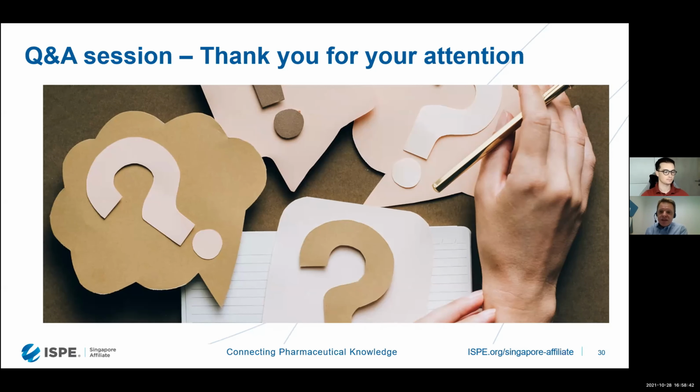I have many examples when the customers see the trends based on the past 2-3 points, and then they draw a straight line and say, oh, the device will go out of tolerance pretty soon. So they start to do the adjustment. Well, it's too early. Adjustment can actually bring the wrong results to the whole idea of calibration. So trends are not linear. Trends are complicated, and that is why we take a lot of factors when we do the prediction. So it's not only the current trend, it's the age of the device, it's the conditions where the device is used, because these curves we'll see in practice are very, very different in all possible situations.